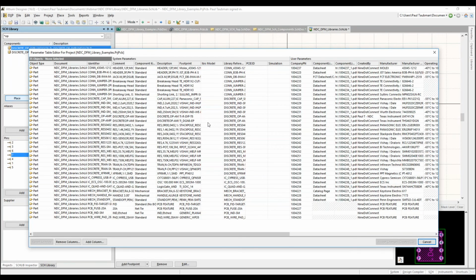And so when you use your database link tool or your database library tool, it goes to the database, says, aha, I know where your part is, I know the name of your part, and Altium can pull it in at that point. The key thing I want to drive home is that there's no way of actually inserting or embedding the library symbol or the footprint into the database. It's still maintained as a separate file outside the database, regardless of the database system you're using.